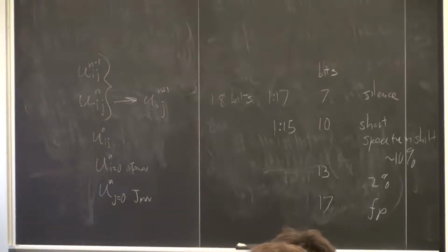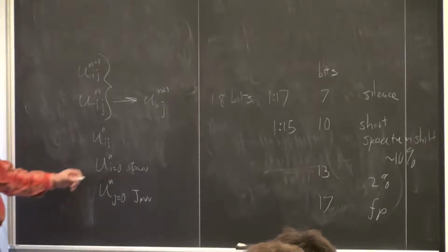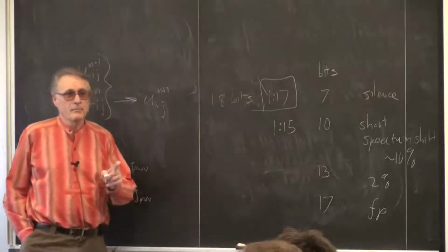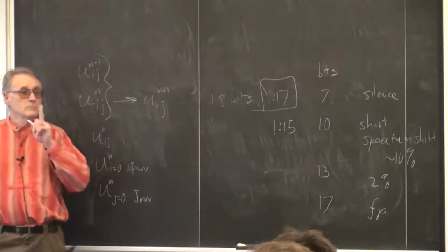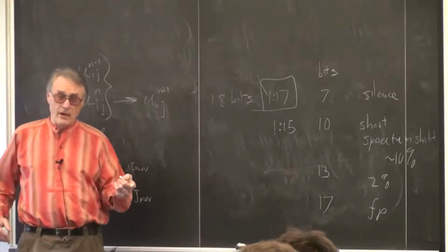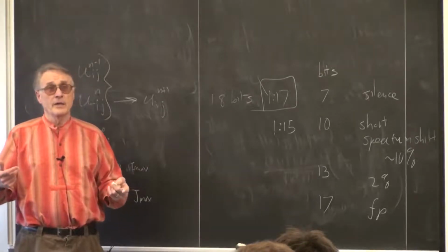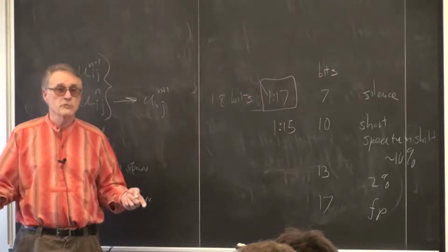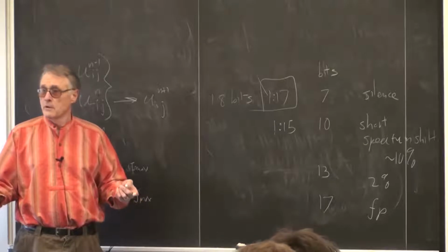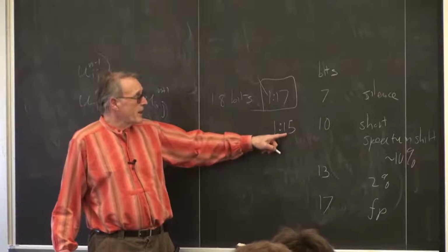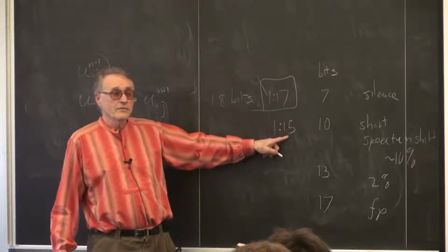So I would say that most of you are going to use probably 1.17 format, a sign bit and a binary fraction. You could think of this as line out through the audio port being plus minus 1 volt. It turns out if you set the gain to 1, line out is plus minus 1 volt. So what you're saying here is that you have 15 bit accuracy on a 1 volt signal.